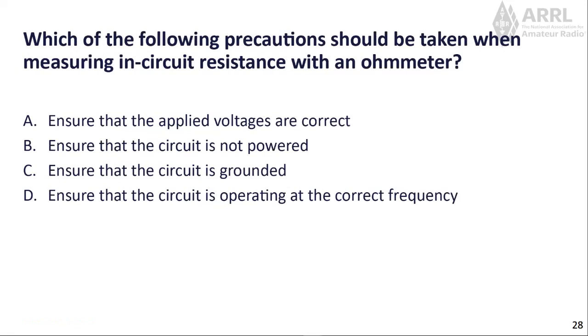Which of the following precautions should be taken when measuring in-circuit resistance with an ohm meter? And the correct answer is B, ensure that the circuit is not powered. Unplug the device.